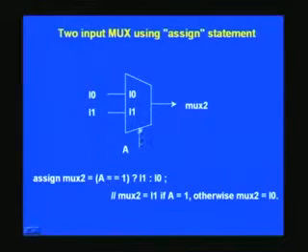Here you have a select signal, and this select signal must first be put here, within brackets if you like. This is not the only way of writing. In fact, you can dispense with all this, including the brackets, and just have plain A, and then also it will work. Or if you want, designers normally prefer putting 1'b0 or 1'b1 like that, because that gives an indication of how many bits of precision the signal has. Here of course it doesn't arise, and it need not be necessarily this alone. We can have even a multi-bit thing here as an assignment.